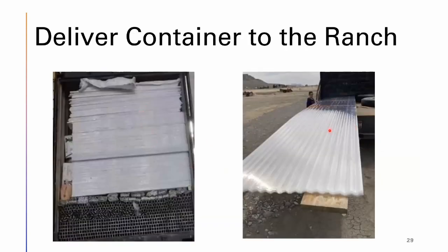Okay, so on the right here, these are 46-inch by 19-foot long corrugated 2-layer polycarbonate panels. $95 each on a per square footage basis. It's the same price as your single layer Home Depot. It's actually a good product. The R value is not nearly as good as your flat multi-layer stuff. I wanted to show you.